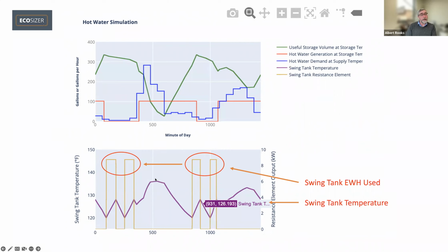And then we hit another little recovery blip, right? As it starts cooling, the tank senses that it's cooled, it turns itself back on, and then people leave, and there's a bit of a draw pattern, enough to keep the supply running through the swing tank and giving it to the building for a period of time. Everything rebuilds and functions properly, and then people come back, and the cycle starts again. And so what you're looking for here, if you're really trying to make the most efficient plant that you can, you want to see that electric resistance consume the least amount of electricity that you can.